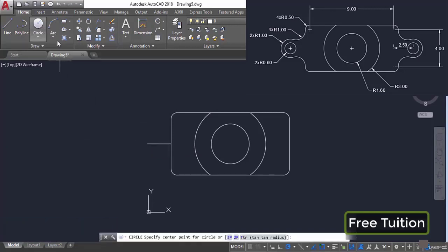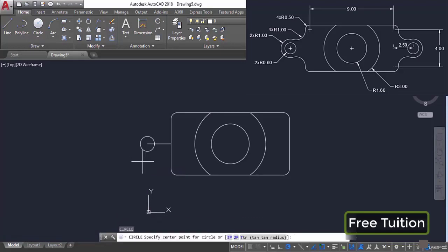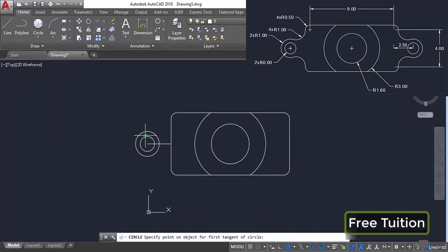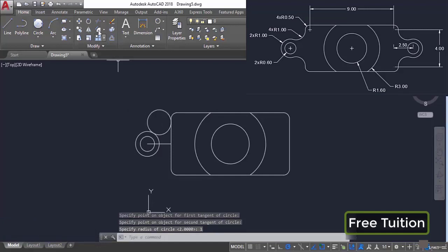Now we need to go to the circle tool and click on this endpoint and make a circle with a radius of 0.6 unit. Press enter again, and this time again go to the same point and make another circle with a radius of 1 unit and press enter. Now we need to make a circle which is tangent to this circle and tangent to this line. So I'll go to the flyout, select tangent radius, and I'll click at this point, then at this point, and enter a radius of 1 unit and press enter. There we have it. Now we need to trim it. So I'll go to the trim tool, press enter, click on this point, and there we have it.